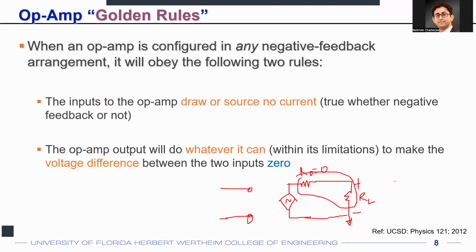I mean, there would be a voltage division, but that voltage division is RL divided by RL plus RO. And if RO is equal to 0, which is the case for an ideal op-amp, that voltage division ratio will be equal to 1. Right? So ideally, you want your output impedance of the op-amp to be very small, ideally equal to 0. It may not be possible to create an op-amp with an RO equal to 0. But the meaning of this sentence is that if your RO is very close to 0, you can drive any resistance that you have.